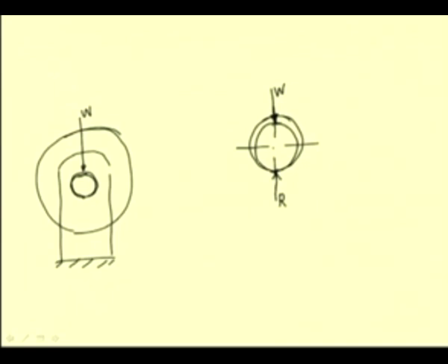When, let us say, we give a small rotation to this axle, then because of the friction that exists, the axle climbs the journal. Because no slippage occurs at this point, and with respect to this point, this axle tends to move, and so new points of contacts happen, and slowly the axle tries to climb in this direction.